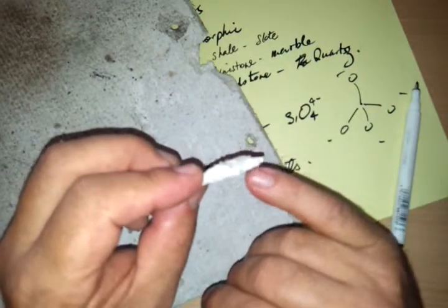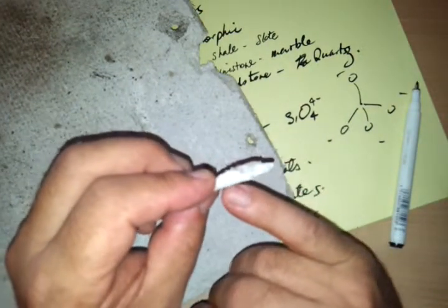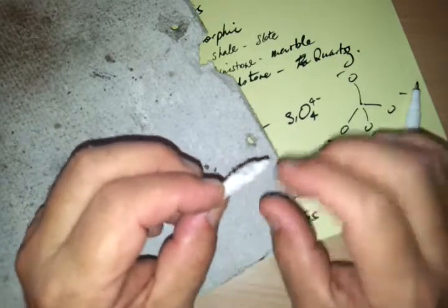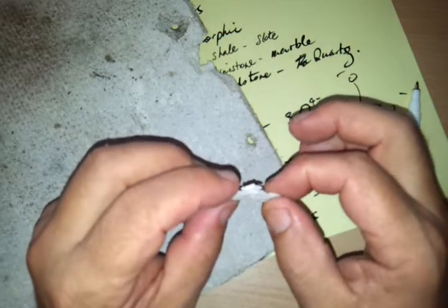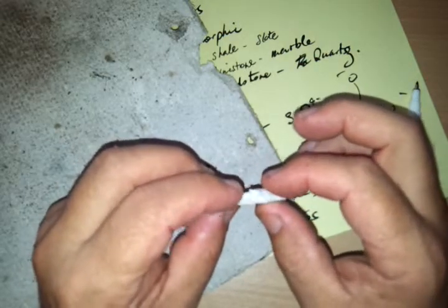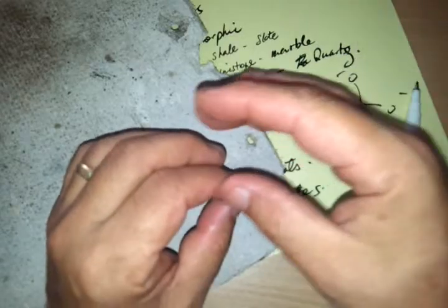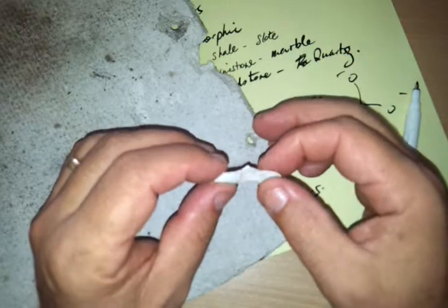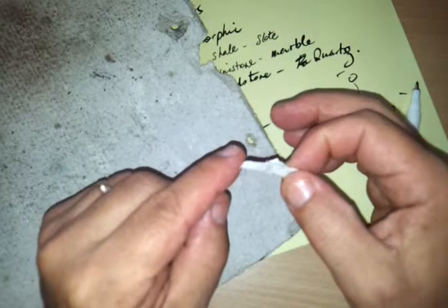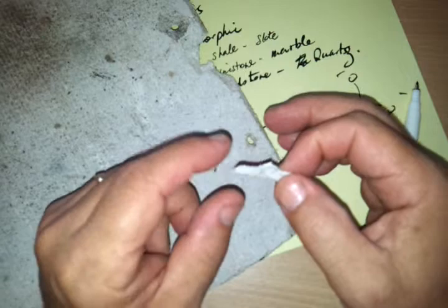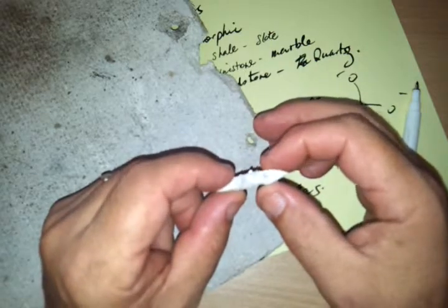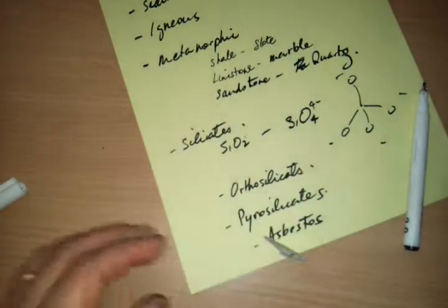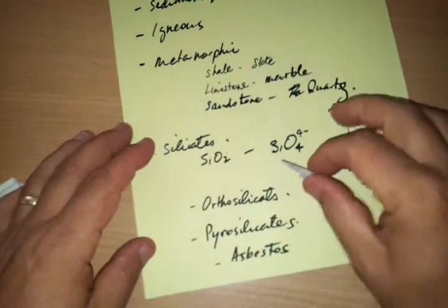So asbestos had strong tensile properties, and we'll talk about why that is, because ceramics traditionally don't have good tensile properties. These tiny little fibres could be released, and they broke along lines, along these silicon chains, creating very dangerous little things that could be inhaled. You can just see a little fibre there near my finger that can be inhaled, and they would cut through people's lungs and create asbestosis. Very problematic. So, okay, fibre reinforced concrete like this doesn't have the same properties.